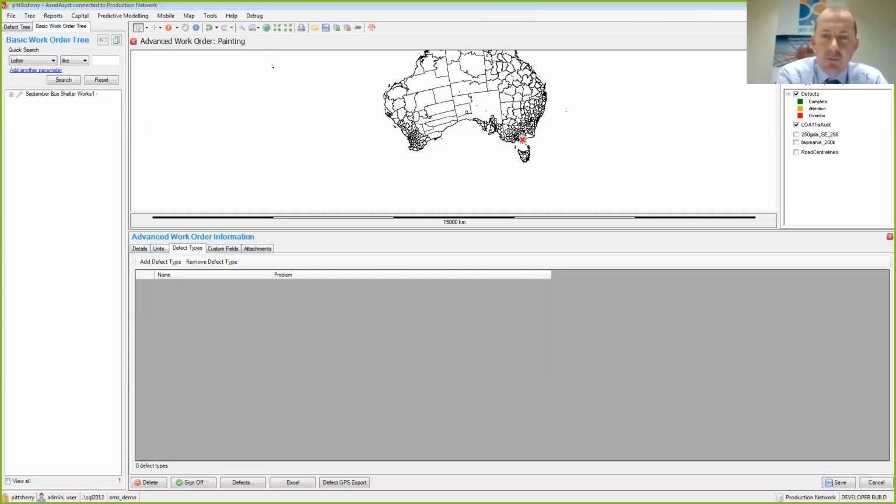This is quite helpful for certain types of road approach defects that might occur relatively regularly but be treated through a program of grading gravel roads, so you can find those, put them on that type of work order and then have them closed out periodically.